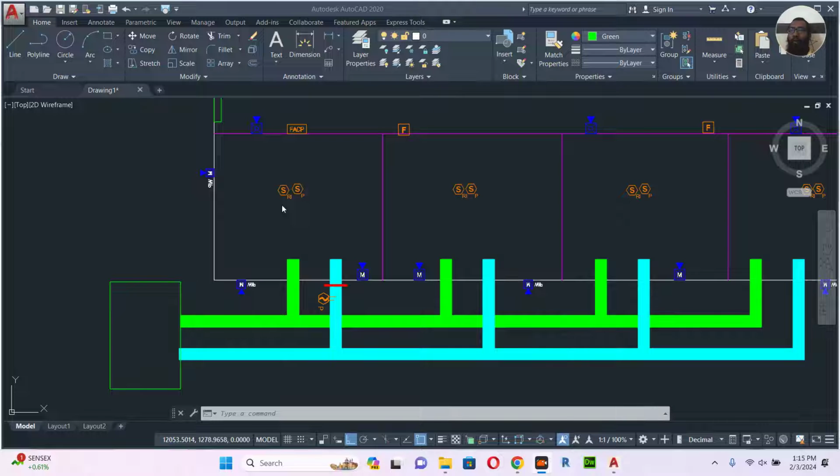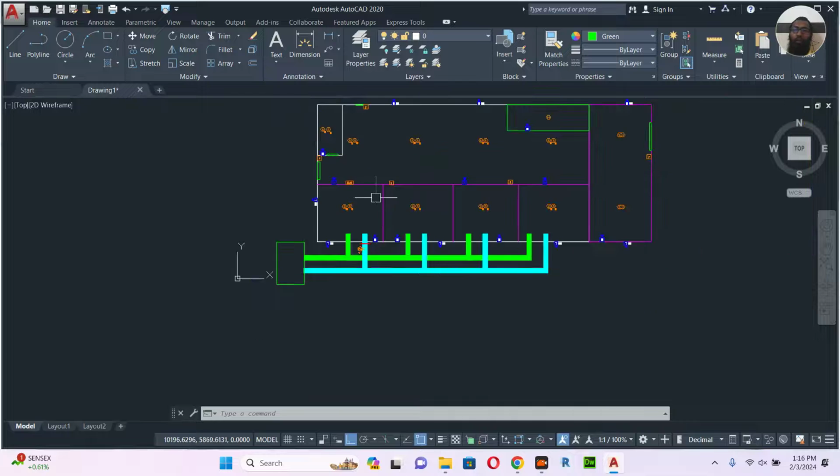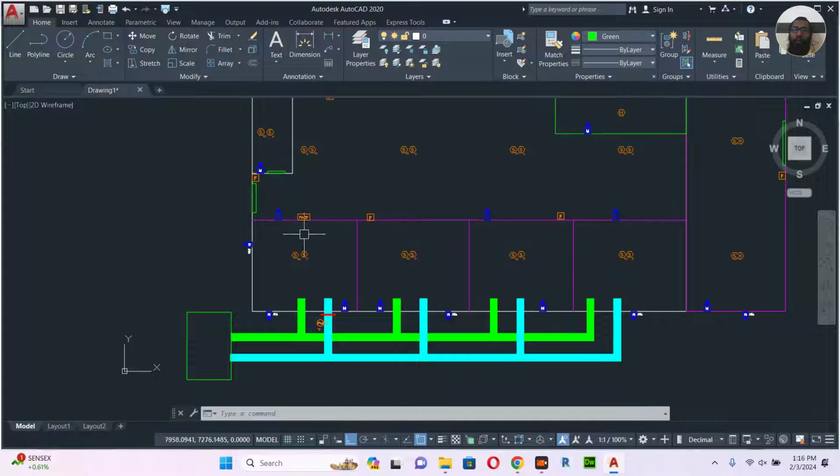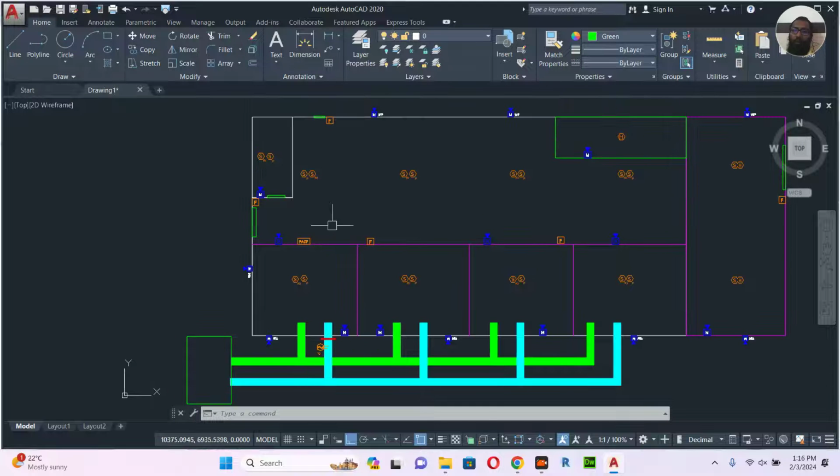So what is the next step? The next step, exhaust will start to work. Exhaust will start to work. So normally every room will not have exhaust. The exhaust normally is in the big areas and rooms. So in case of fire, the people have to run away, meaning run outside. So the smoke will already be spread here. So the smoke can be sucked through the exhaust.